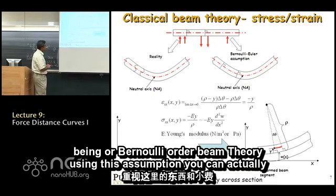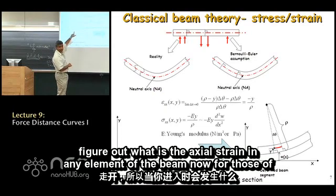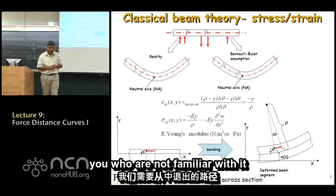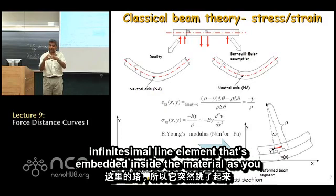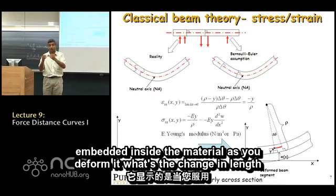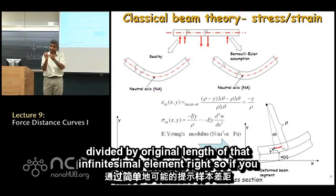Using this assumption, you can actually figure out what is the axial strain in any element of the beam. For those of you who are not familiar with it, strain just refers to, if you took an infinitesimal line element that's embedded inside the material, as you deform it, what's the change in length divided by original length of that infinitesimal element, right?